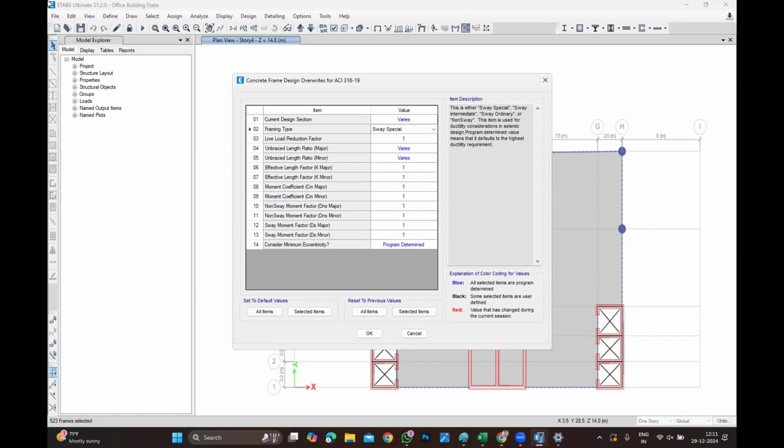The reason is two kinds of things. You might have seen in the manual calculation of column capacity, it is the combination of two: concrete capacity plus steel. Even if you don't provide the steel, you still have the capacity. It is very little, but you still have the capacity.